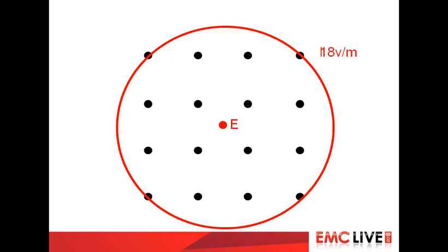So if we put numbers in there, we get 18 volts per meter. We can't be less than that, if you remember. We have to be minus 0 dB plus, and a maximum of +6. There's a certain window that these points must fall in. So we've got 18 volts per meter there. The center point has to be between 18 volts per meter, cannot be less, and 36 volts per meter, cannot be more. But if we do the math, and again it's in the supporting notes, we end up with 25 volts per meter. Now, what does that mean in terms of our system design?